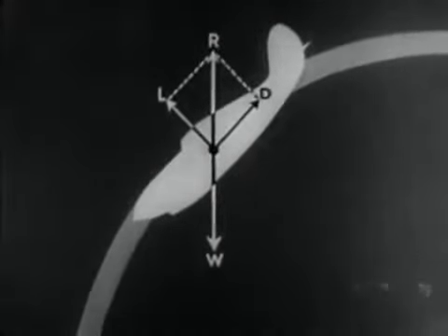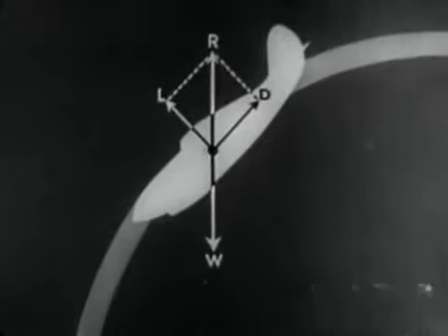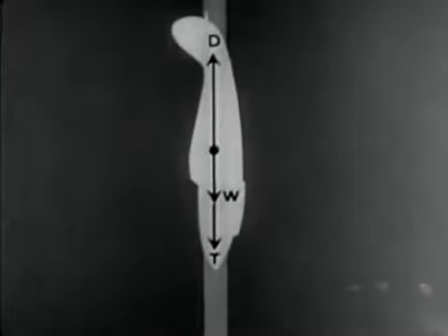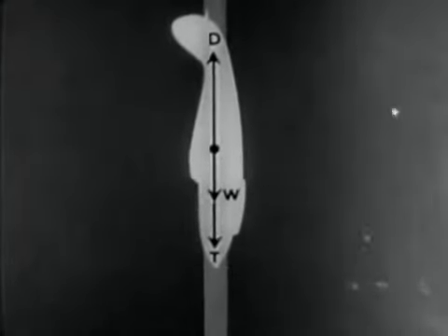increases. Lift decreases, since in this attitude the weight of the airplane is opposed by the resultant of lift and drag. As the flight approaches the vertical, speed increases until the terminal velocity is reached in the so-called vertical dive. In this condition, lift is zero, and the weight of the airplane plus its thrusts are opposed by drag alone.